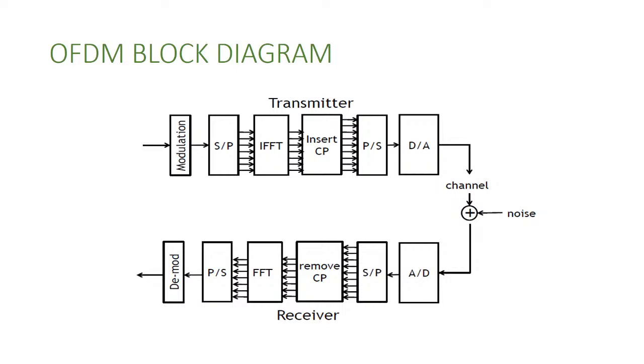So like the modulation, then signal processing. Modulation is nothing but whatever input we are providing towards the transmitter. According to the device, it automatically modulates that complete signal. Then that particular signal is converted from serial to parallel. With the help of inverse fast Fourier transform, we convert that particular signal, and we send the transformed signals to the carrier. Once the carrier is taken, the parallel to serial is converted, and since we want to transmit through wireless, the digital data, because whatever we are nowadays transmitting inside the mobile completely comes under digital, is converted from digital to analog.